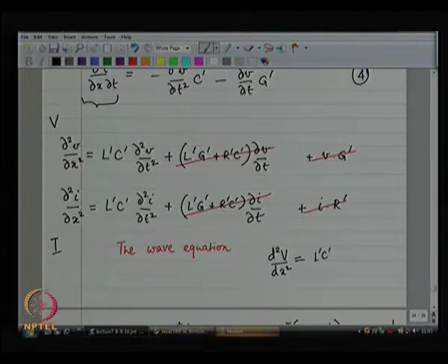What is the second derivative of the phasor V? So, if I have got V cos omega t, or let us say I have got V times e power j omega t, then the second derivative is going to give me omega squared times the original. Is it omega squared or minus omega squared? Minus omega squared. So, cosine to sine and then sine to cosine again. So, that is one negative, or you can think of j omega times j omega is minus omega squared.